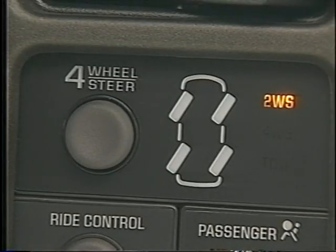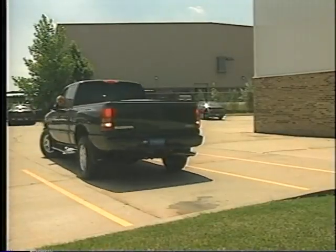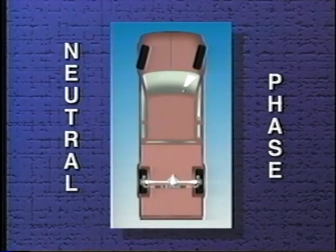I'll take a look at another video here to give you a little more detail about what's going on. With the mode select switch in the 2-wheel steer position, the rear wheels are locked in the straight-ahead position, and the vehicle steers and operates in the same manner as a normal 2-wheel steering vehicle. This normal 2-wheel steering is also called neutral phase. The rear wheels do not move relative to the front wheels.